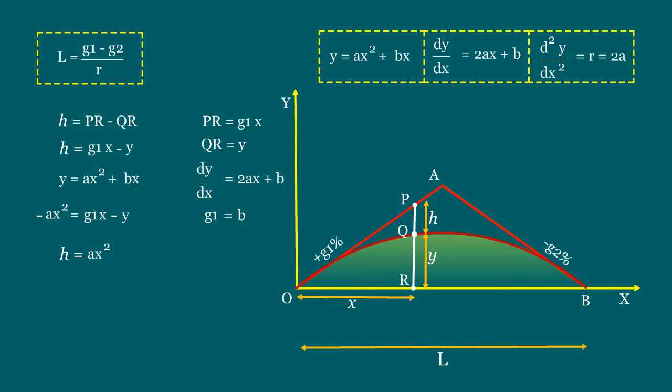In vertical curve design, this constant is denoted as k, so we can write h equals kx square. x is the horizontal distance in algebraic formulas, so x can be replaced by n, because n is the total number of chords with uniform intervals, counted from point O, which covers the total length of curve L. Finally, this can be written as h equals kn square.